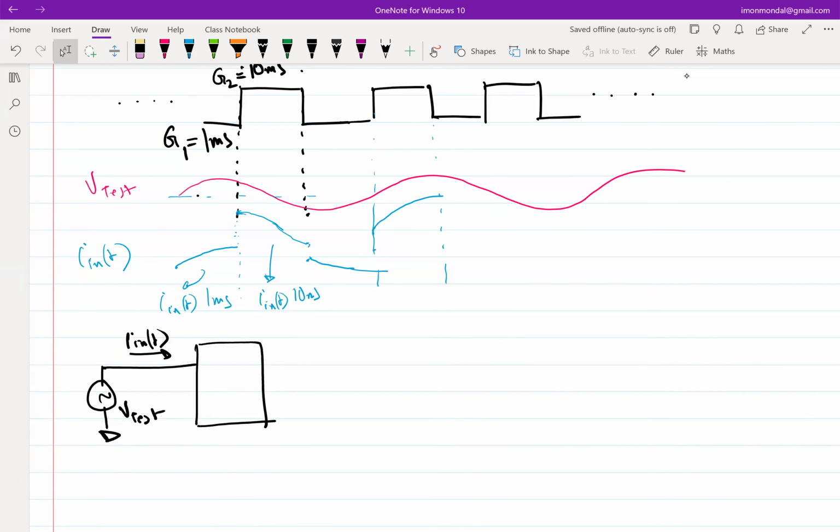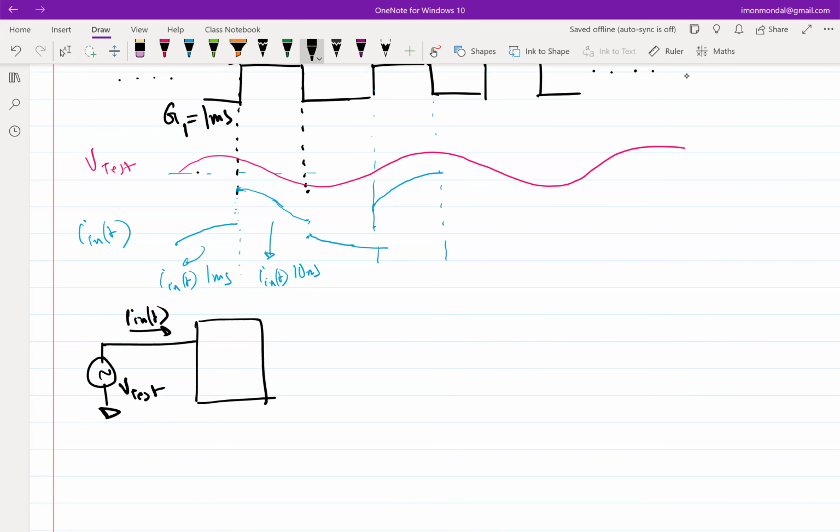The simplest thing to generate in an IC is a square wave. So let's say you have a square wave available to you. You can use one transistor, connect this to the drain, and to the gate of the transistor, the higher part of the square wave would allow a current to pass through. Okay, so can you repeat again?